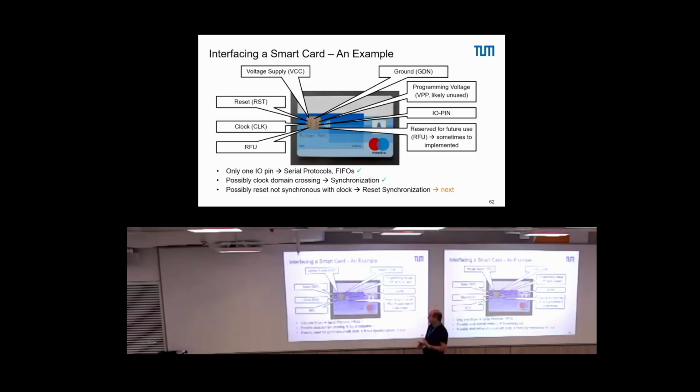Okay, so if we talk about reset, which two different types of reset do we have, and what are the respective benefits and drawbacks? So we have two basic kinds of resets, right? And the question is, which are those, and what are the benefits and drawbacks of it? So you said already asynchronous resets immediately. So it's also in safety critical applications where you do not want to rely on the clock, or you have a super slow clock and want to react faster. This is a good fit.